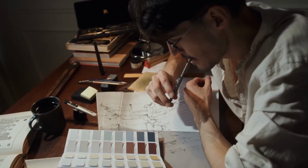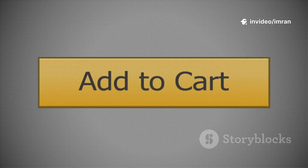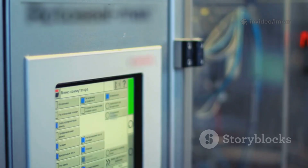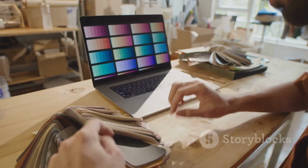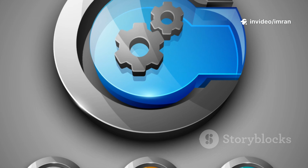The Layer Properties Manager is your central control for all things layers. Here, you can create, delete, and modify layers. Find it under the Home tab, Layers panel, Layer Properties. It's best to keep this palette open. Create new layers with the new layer icon.